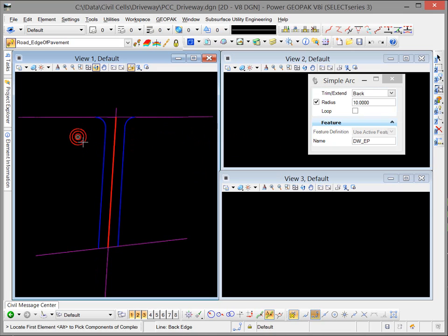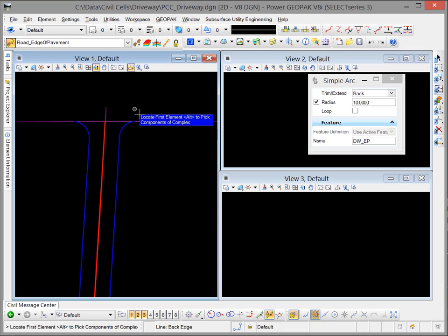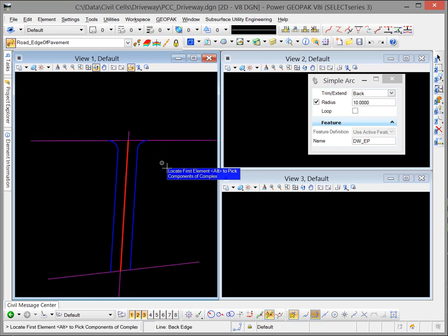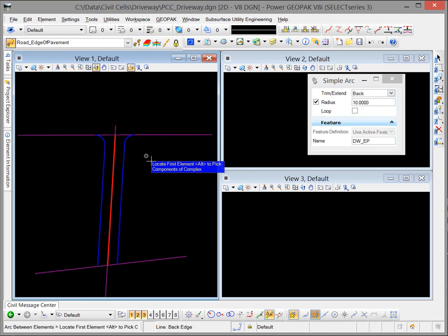And so now we have our geometry, our horizontal geometry, constructed for the edges. Now, the next thing that we want to do is begin to start thinking about vertical. And so the first thing that we would do there is we need a seam line that is going to be placed here for the boundary of our terrain model. But to do that, we first need to establish vertical on the one line that it is going to be required, and that's going to be this edge.